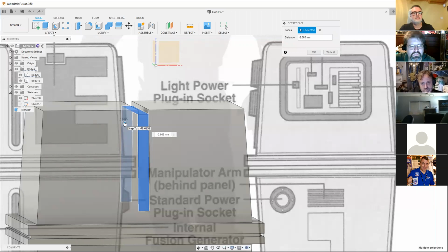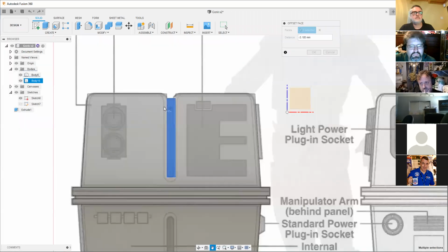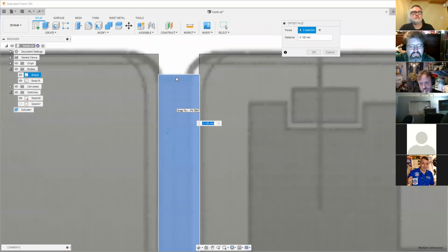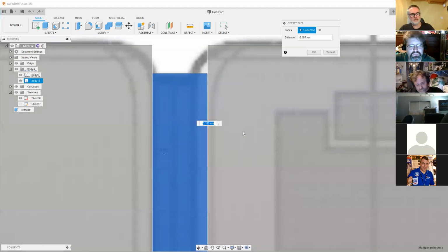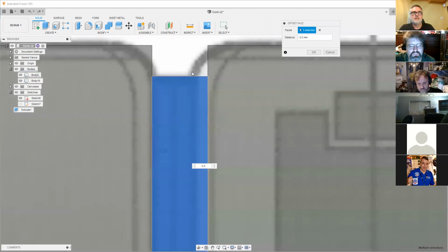And then you were just adjusting the press pull to get the top to line up with the drawing. Is that correct? That's right. Yeah. So I got it thereabouts, and then what I can do is type the measurements in. I'm going to put 3.5 millimeters in there, and it lines up then at 3.5, and then I'm going to click OK.